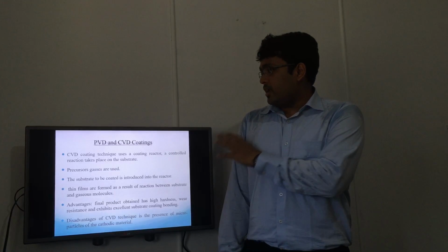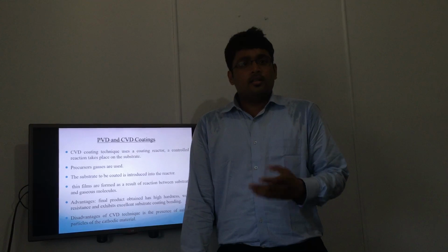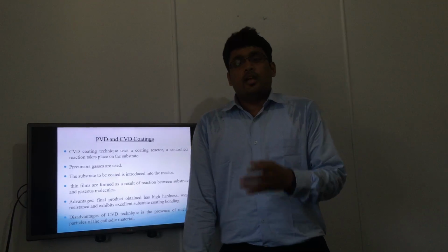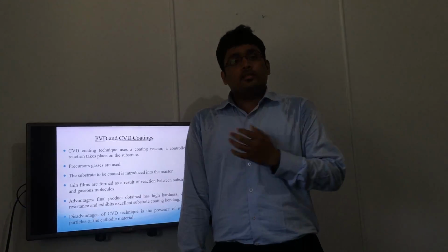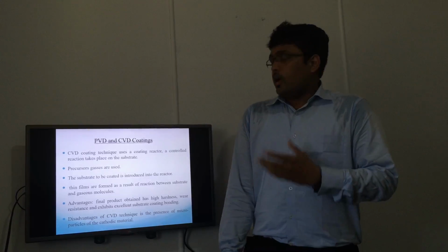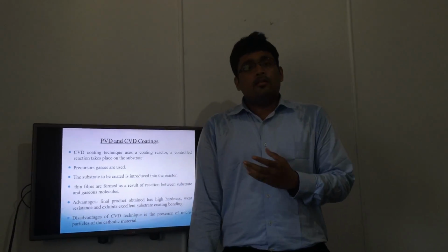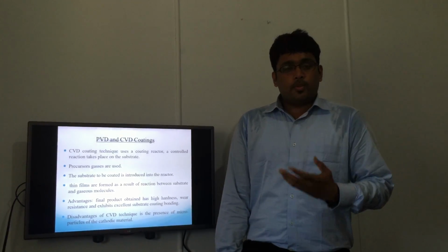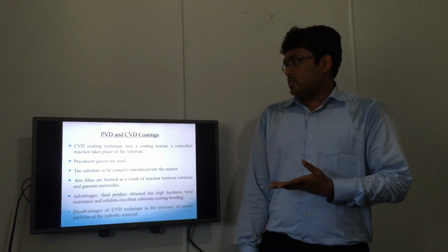And then the advantages of this technique are that the final product obtained has high hardness, higher wear resistance, and it exhibits excellent coating finishes. And then the disadvantages. While coating titanium alloys, the main problem with CVD coating is that the presence of microparticles hinders the coating rate. So that is the main disadvantage of this technique. So we need a technique where the microparticles can be eliminated so that we get better finished products. So this technique is not suitable. So moving on to the next technique.